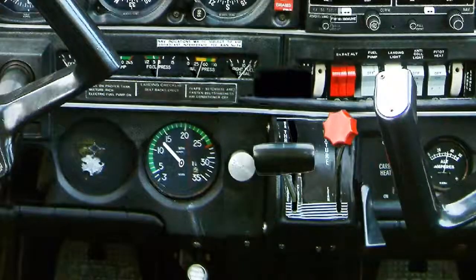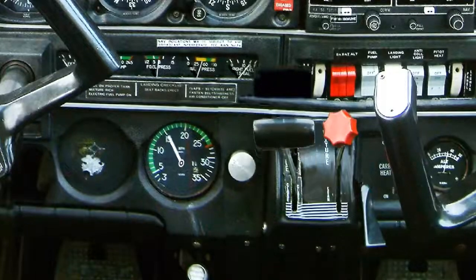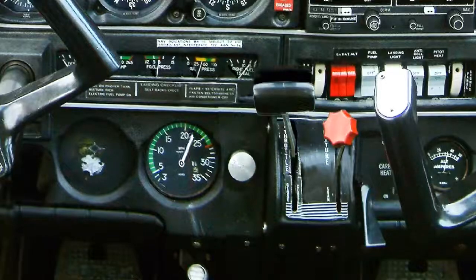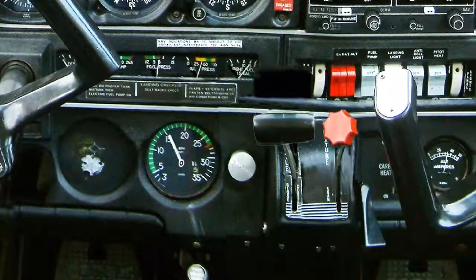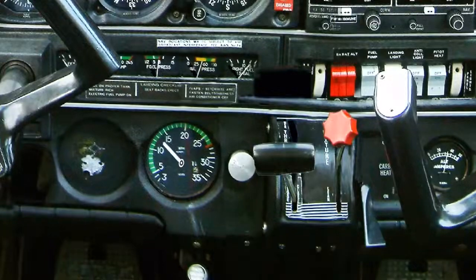Specific fuel consumption is affected both by engine design and the way that the pilot operates the engine. Correct operation of the engine by the pilot is essential if the optimum performance figures are to be attained. Opening and closing the throttle smoothly and relatively slowly will go a long way to obtaining both good specific fuel consumption and long engine life.